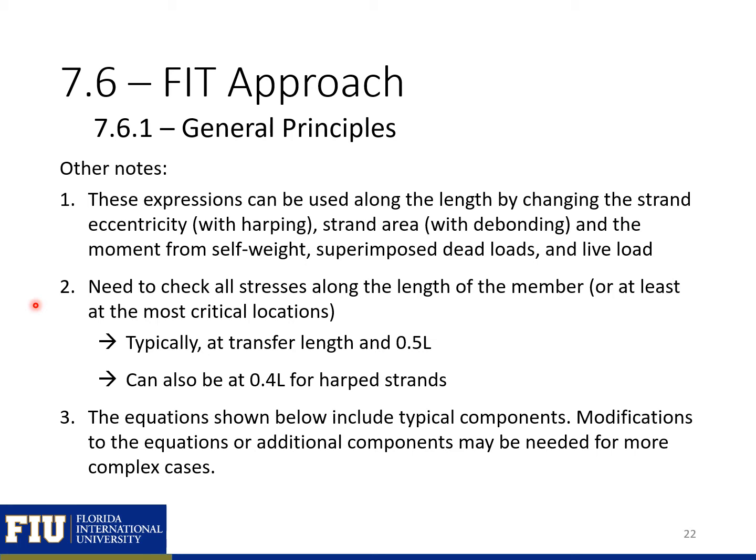So typically, if we're doing this by hand, we may just check at the end of transfer length and at midspan. But if we have harped strands or debonded strands, the stresses may control somewhere between the transfer length and midspan. So you may need to, or you should, check at other locations. If we're doing hand calculations, then 0.4L is a good place to check. And the equations shown below include typical components, but you can also add other components for additional moments or axial loads as needed for more complex cases.